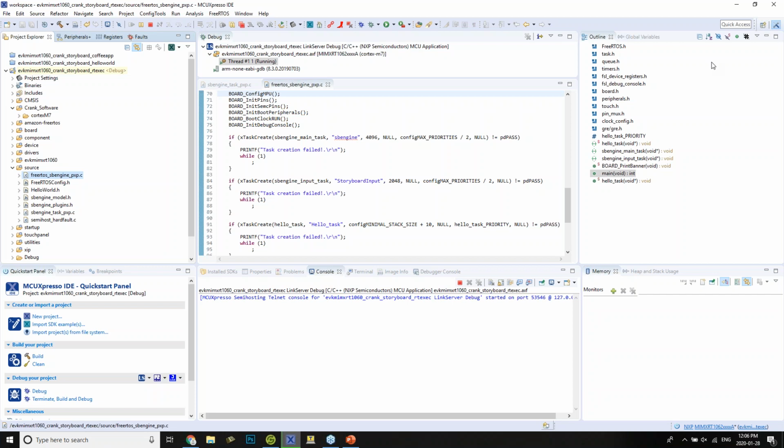We also leverage the PXP acceleration to help the buffer swap and transfer, so we get a little extra performance out of that. You could configure for a single frame buffer configuration if you wanted. The one difference with that is if you're looking to do full screen blends or fades, things like that, you may not get the effect you're looking for. To avoid tearing and things like that, you need the second frame buffer.